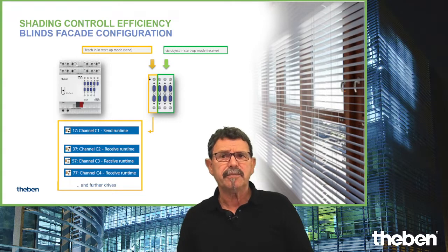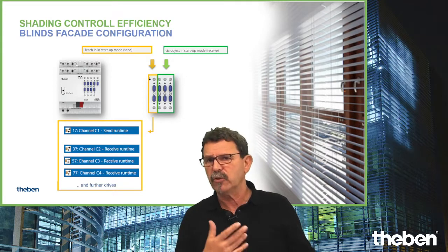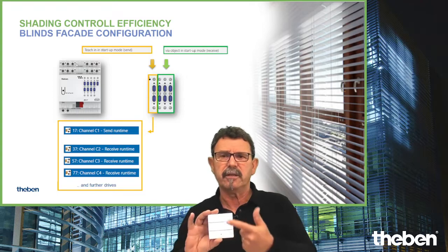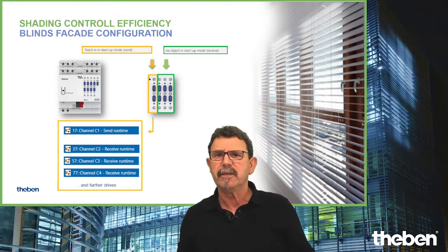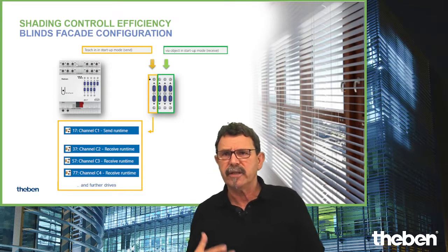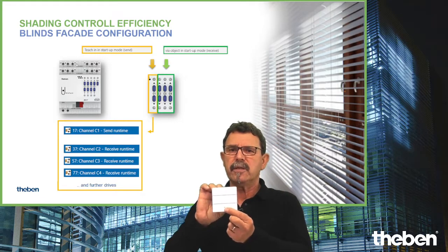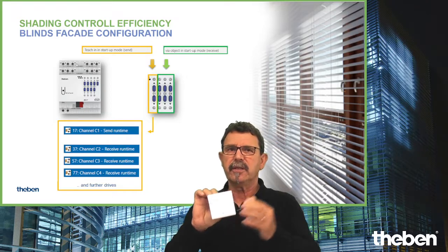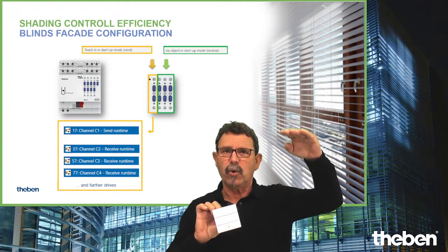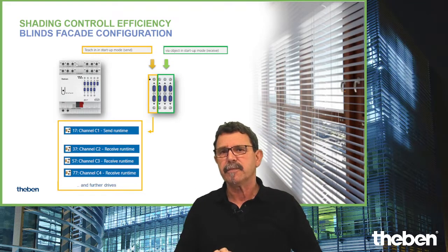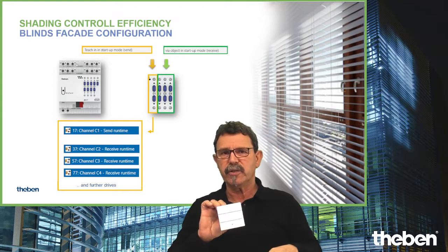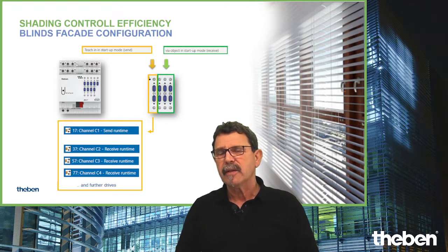You can start the teach-in function with the bit objects. So you can do it with a bus monitor, or you can, for instance, do it with a push button, send 1, so then teach-in is starting. And then finally, pressing the down, so now you run down all the blinds and stop at a reasonable position. So then these actuators know exactly what the drive time is.